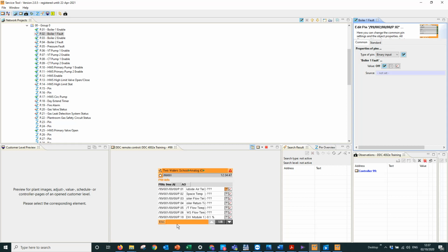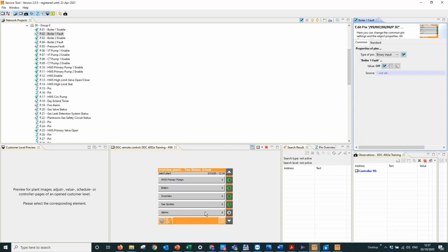With regards to temperature logs, any variable can be enabled as a log. This would be more for the engineer's level at this stage, but if we go to the customer level, in the software we will indicate parameters that can be logged. As you can see, it's boiler flow temperature, boiler return temperature, for example. You can click on the log. The red areas mean this is when the outstation's literally been offline, so it's only been recently powered up.